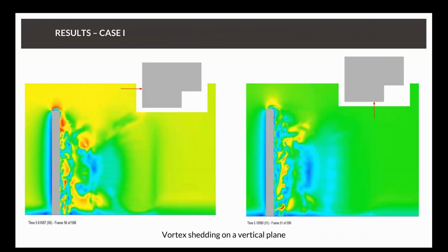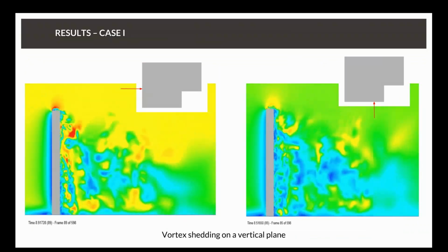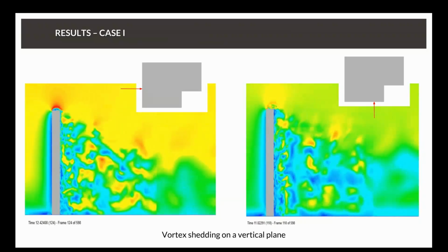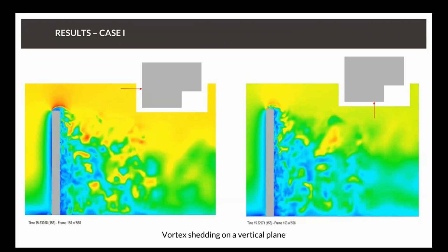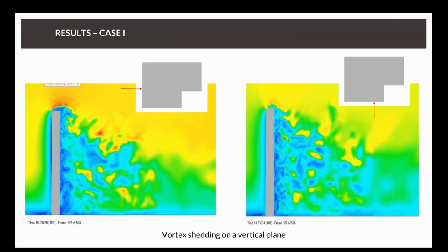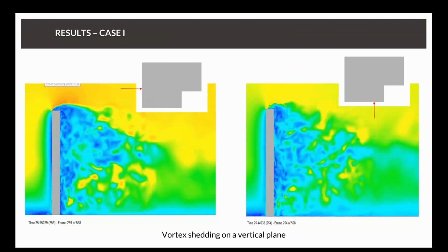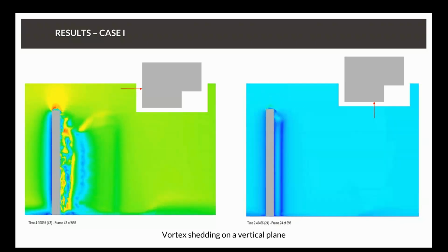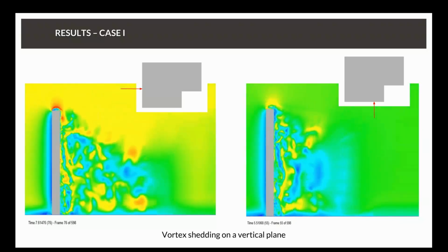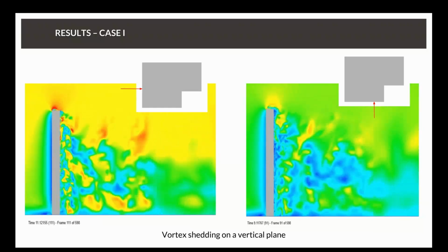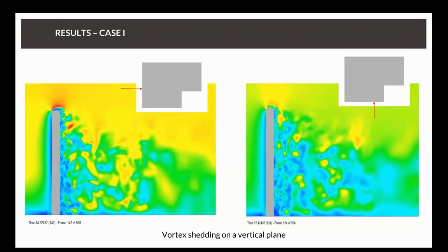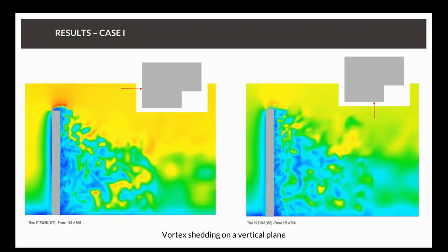And the same on a vertical cut plane. I thought I'd show these just because they look so beautiful, and it's really amazing to see something so chaotic and transient but also accurate. You can see the flow almost looks like it's traveling back towards the building, so there are some huge vortices and some negative pressures that are essentially sucking the air back towards the building behind it.